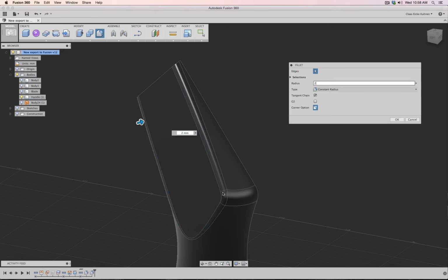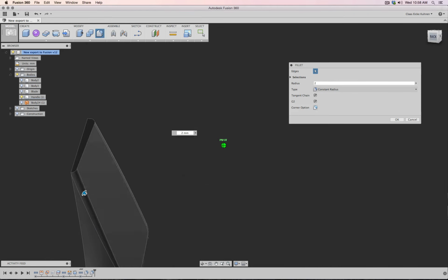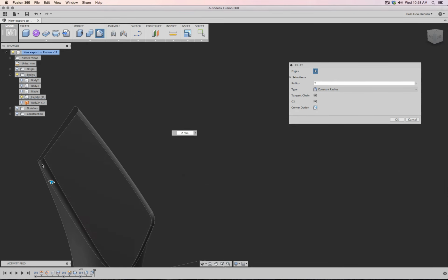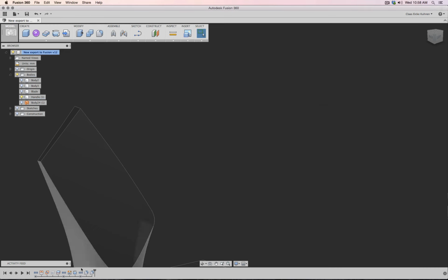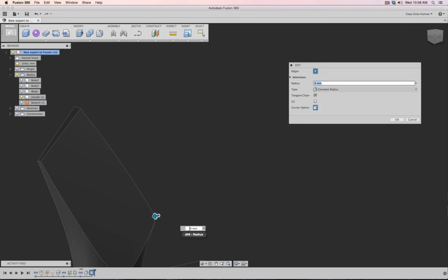Yeah. You see, by having this edge rounded first, I get this type of a rounding. I don't really get any sharp there. So if I change the corner option, it doesn't really do anything. But maybe that radius is too big. So cancel, go back to here, add it, and maybe say 1mm, and apple click, add those parts.